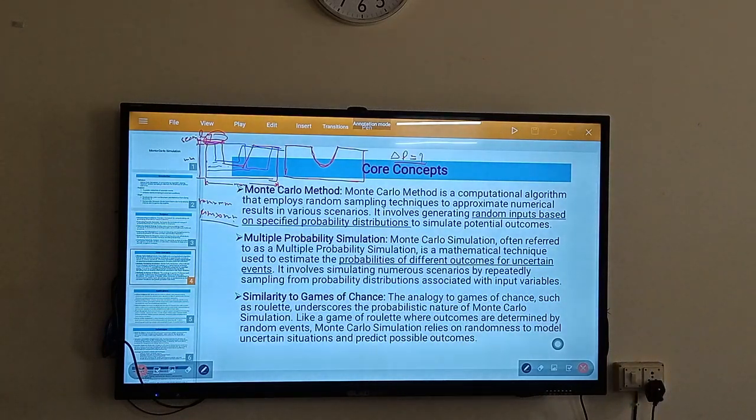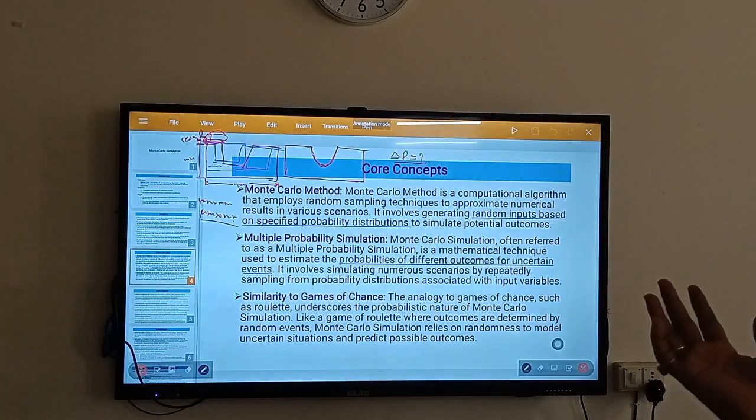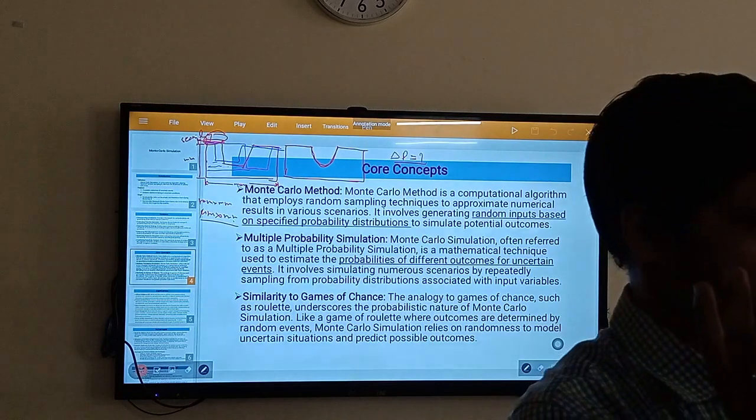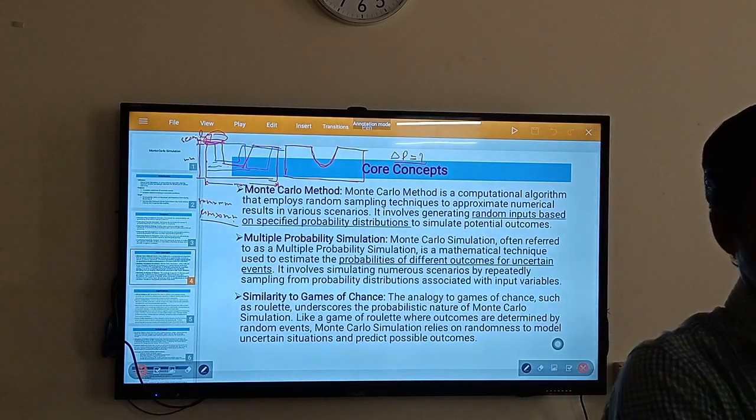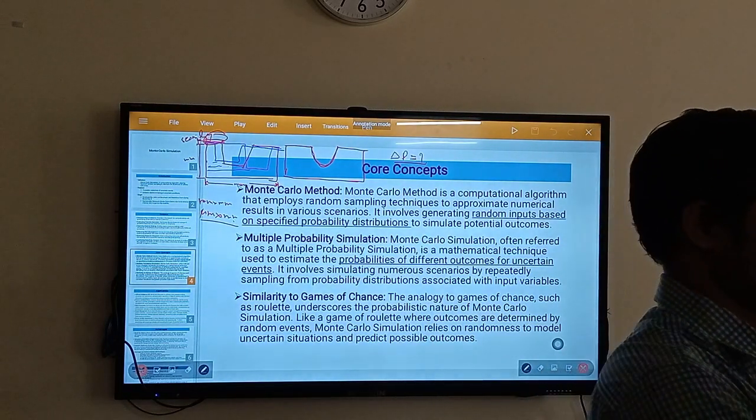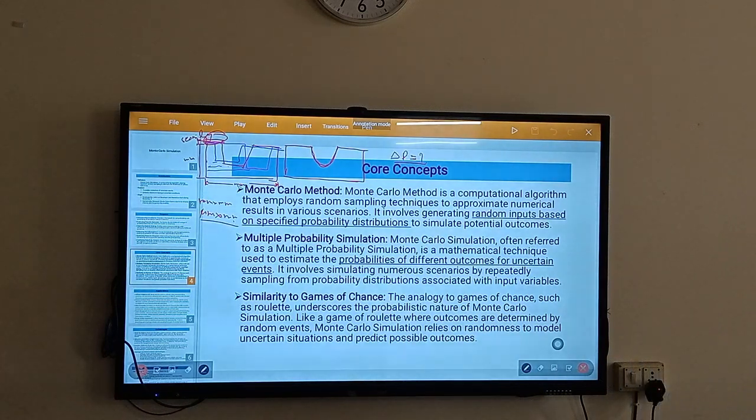So I will not bother about the absolute pressure first of all, because it has nothing to do with that. Differential pressure is itself a relative term, because differential pressure can be calculated as the difference of 2 bar minus 1 bar. I can also calculate it as the difference of 10 bar minus 8 bar. My reference will change and my input will also change.